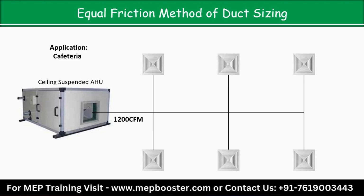So if you have selected 6 diffusers and the total supply air is 1200, each diffuser is of how much CFM? 1200 divided by 6, you will get 200 CFM. Means from each diffuser we need to supply 200 CFM.